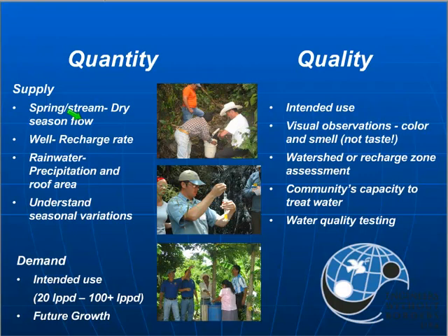I worked on a project in Honduras where there was a water supply system, and the design was done before I got involved, and then I was there to just oversee the construction. And so we were going to go out and just stake out the line, and the money was all raised, people were contracted, everything was ready to go. And when we went out to stake out the line, and I was visiting the source for the first time, it was in the dry season, and the location in the stream where the water was going to be collected with a spring box had completely dried out.